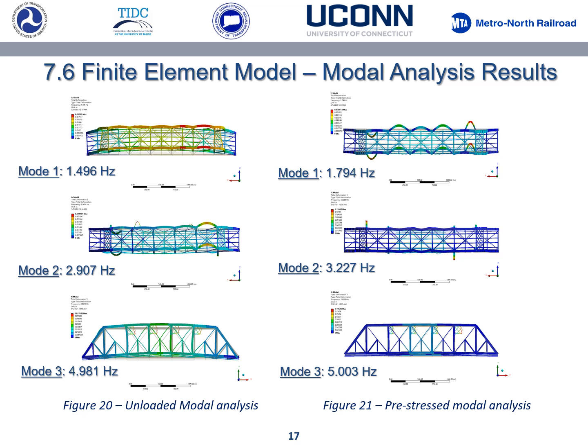That's almost the same behavior as a guitar string. The more tension we give to the guitar string, the more the natural frequency changes, and the sound wave changes as well. So that's the same principle, and we can see the same principle in the mode shapes. On the left side you can see well-defined mode shapes, and on the right side there is less deflection due to the pre-stress.